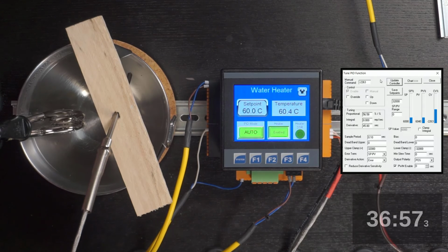Okay, now one thing I want to have a quick discussion of, and that is the proportional term. I haven't played around with the proportional term at all. If I go through and do a calculation on the different proportional terms I might be interested in using, the calculation I came up with was, say, 64 was about the largest proportional term I wanted to use. That would be because of how close to the set point, for instance, when we're heating water that's just been poured in, I want to be before I turn the heater from 100% off to some lower level.